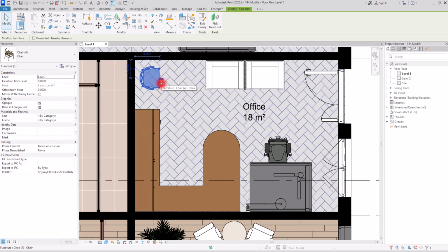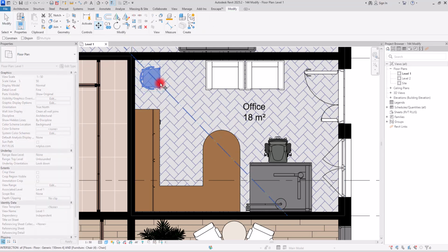But when you want to create walls or when you want to have specific distances, gaps or sizes, you need to use this Move tool. For that, you can click on this part and then click in here. You can use values in here too. For example, I want to move these closer to this part, like 50 centimeters.